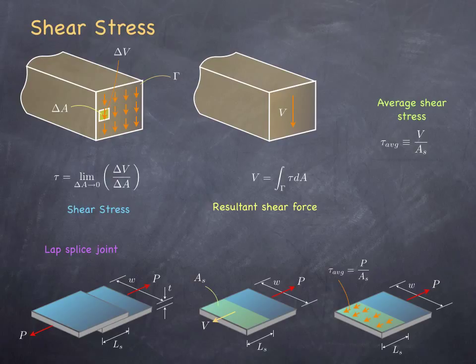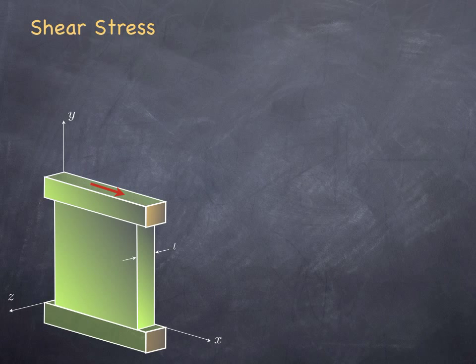Nevertheless, this is just a basic incursion on shear stresses. Let's discover something a little bit more intriguing about shear stresses. So let's assume that I'm doing a hypothetical test on a shear wall or a plate, and I apply some shear force at the top of this wall or plate, while holding its bottom fixed. Let's assume that this wall or plate has a thickness of T. I'm going to isolate a small segment of this wall of size delta X, delta Y, and I'm going to be focusing on a point at one corner of that, at Z.